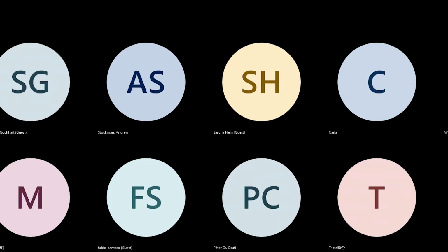Okay. So for Steve, I separate them at this moment. LEDMax is a system specially devoted to measuring colorimetry functions. It's nothing to do with the tuning. It's a human tuning the colorimetry RGB. So that is one way. For the cameras, the SSF, it is just put there. You measure 18 colors, so you use the camera to measure 18 times. You also measure the spectrum 18 times with the spectral radiometer, and then you compute. There's no human involved. That is the typical characterization.